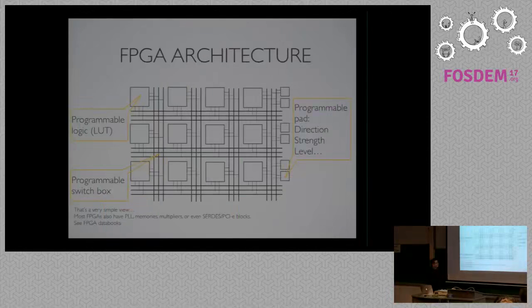It's because it has a very particular architecture, which is composed of a logical block, where you can define the logical function that will be done, and a network of connection that is also programmable, and the user will also define how the signals are routed within this network.